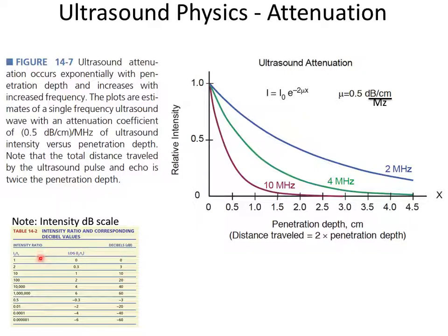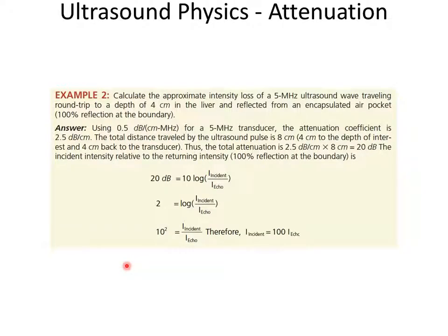It transforms orders of magnitude amplitudes by a log of the ratio, multiplied by 10, so that you don't need decimal points. You can just say 60 dB is a factor of 1,000,000, right? And 3 dB is a factor of 2. So it makes the scale really easy to use, right? It's often used for signal to noise, for example, in audio or other things where you have orders of magnitude. So you should know that.